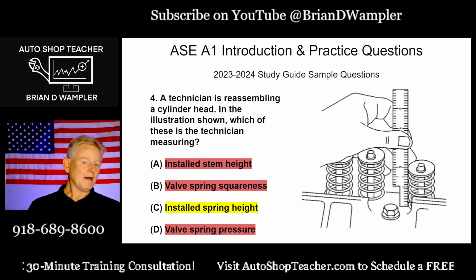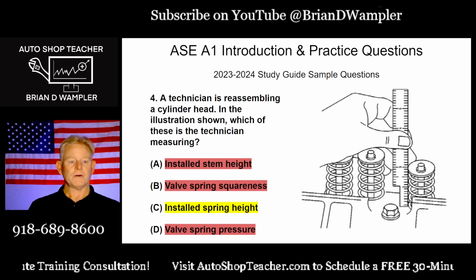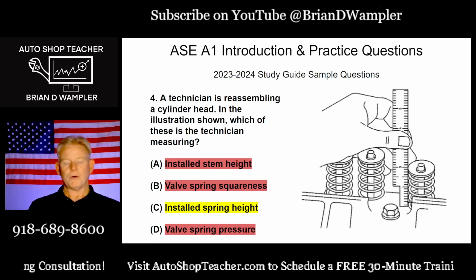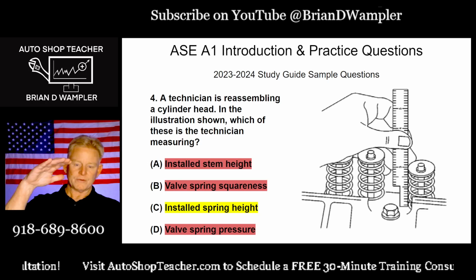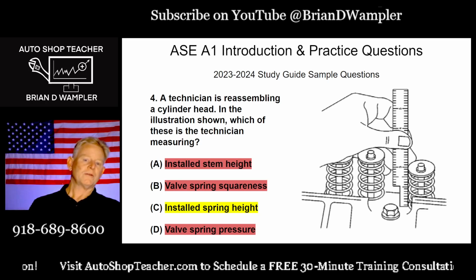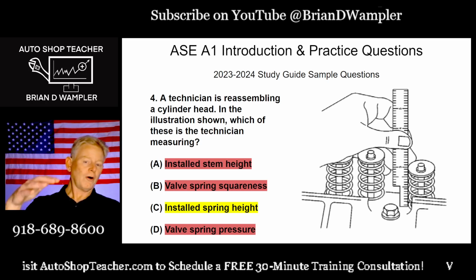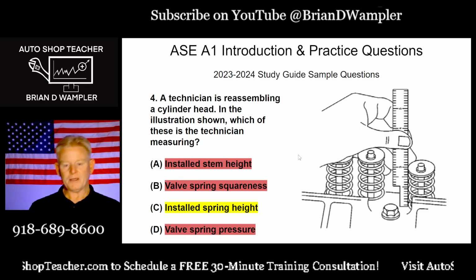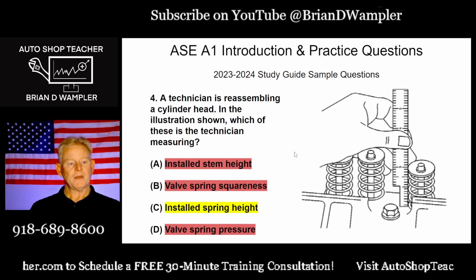If yes, then the installed spring height would be important, because you would want to make sure it wasn't too short, because when the valve gets pressed open, you wouldn't want the coils to be binding. Likewise, you wouldn't want it to be too tall and risk there not being enough spring pressure keeping the valve and the seat in a nice closed position.